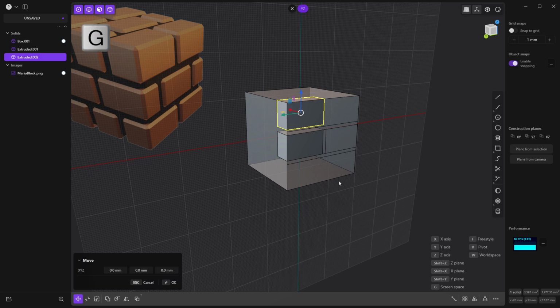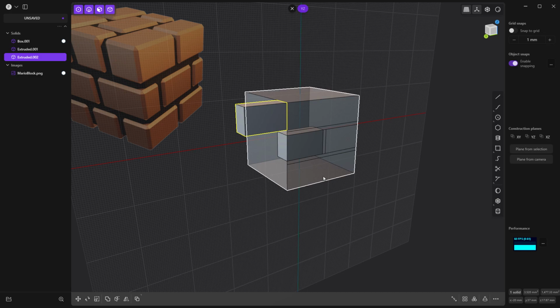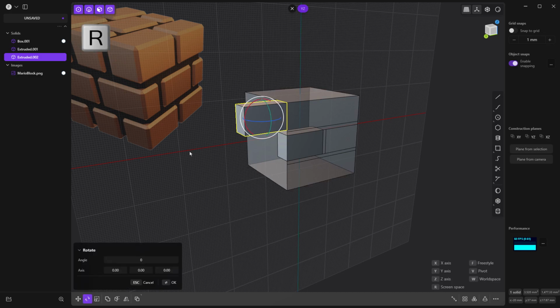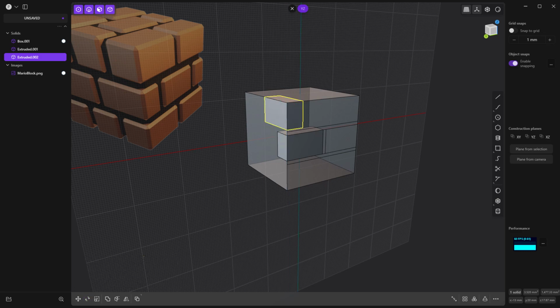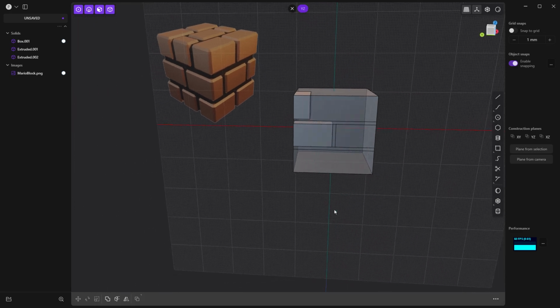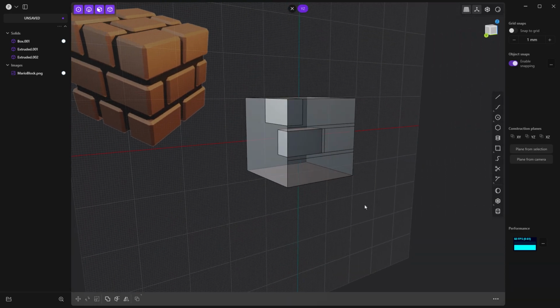I'm going to reset my pivot point with V to this position here. Or I can do Freestyle. Let's do Freestyle for this example. F for Freestyle. So we're going to move from that point to this corner and right-click to accept. Next, we're going to rotate it. Once again, we want to reset our pivot point. So V to reset our pivot point, just somewhere on this edge here. And now we can rotate it about Z, 90 degrees. So manually enter 90 and hit OK. So you can see now we've placed that block in that second orientation.